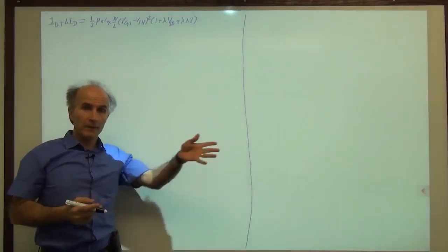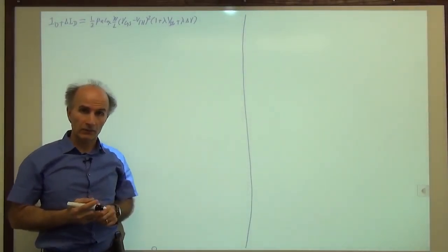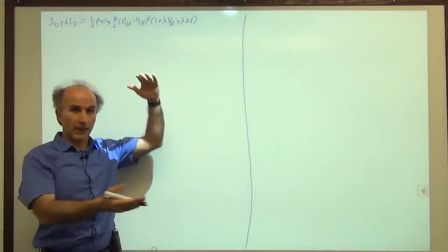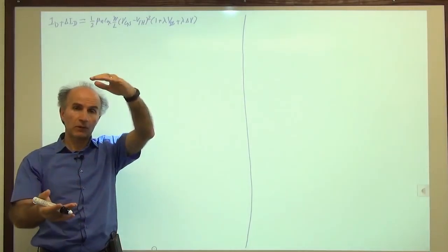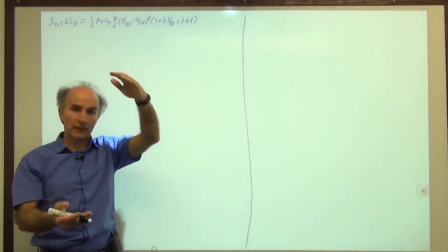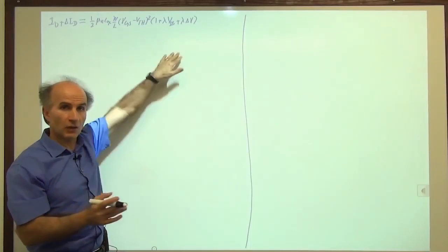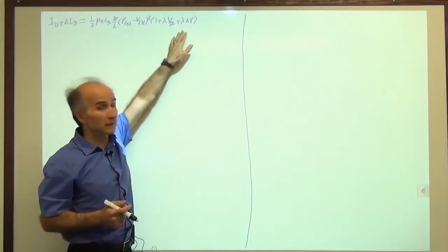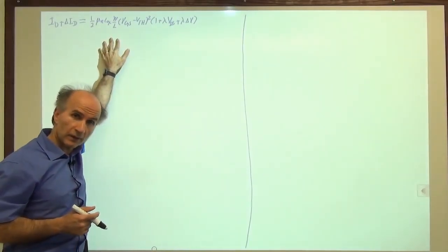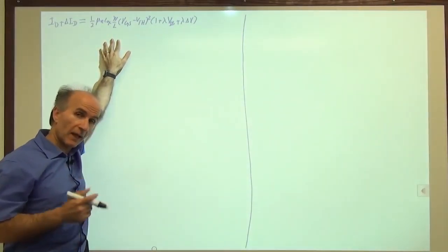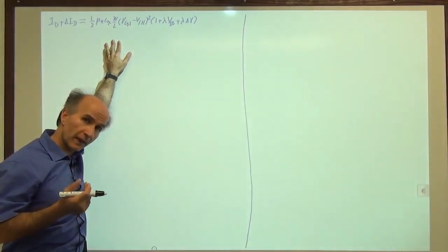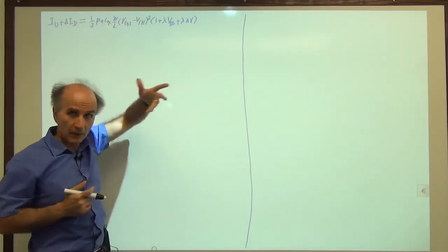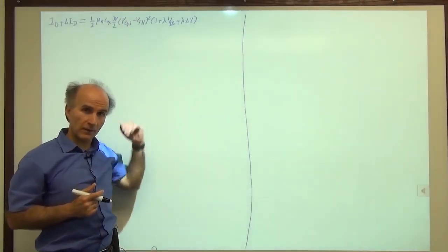Okay, that's exactly what happens in the circuit that we had a minute ago. We are just looking at the general case. We have a battery between gate and source. We have a battery between source and drain, and we increment that battery by delta V. All right, this is the general equation. This is the large signal model, if you will. Even though the changes are small, I start with the general equation. If you remember, last time when we derived GM, we also did the same thing. We assumed that VGS was incremented by delta V and then simplified things, and GM popped out. So it's the same situation here.